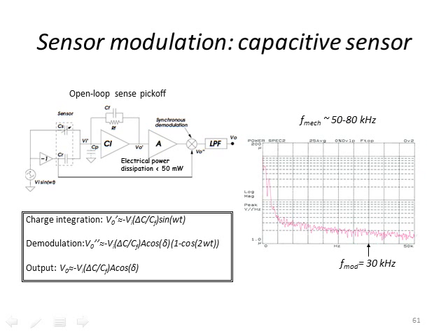What this allows us to do, you'll see on the right-hand side, is a log-log plot with a red trace. The red trace at 0 frequency is the 1/f noise. So what we do is we modulate this at around 30 kilohertz, and we do all of our measurements at 30 kilohertz, where we're really at the noise floor of our measurement circuit. And then we can get rid of this 1/f noise associated with the sensors and all of the electronics involved in doing the measurement.